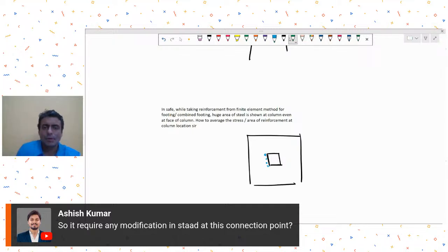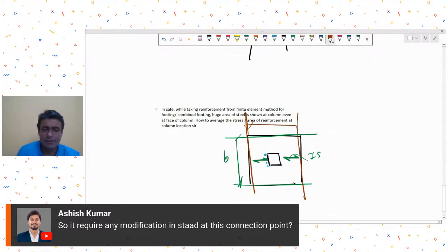So a good way in isolated footings, at least, is that you make a strip width, equal to, let's say, this B, when you are looking for this span bending, and then you can create a strip width which is having this dimension B2, let's say, when you are looking for this span bending. So when you create these strips, the software will do some internal averaging.